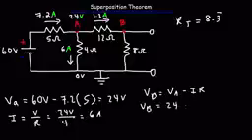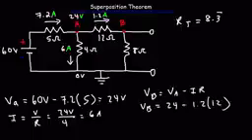So the potential at A is 24 volts minus 1.2 times 12. And so the potential at point B is 9.6 volts. And if we divide 9.6 by the 8 ohm resistor, we're going to get this current, 1.2 amps, flowing through the 8 ohm resistor. So that tells us that our numbers are good, our math is good rather.